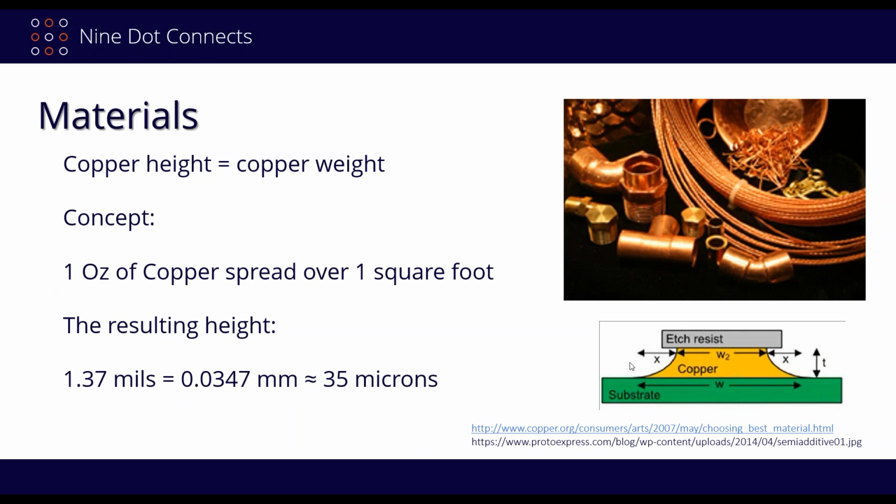What happens here is that, remember, you're working with copper sheets. You put an etch resist on top of it, and then you put this in a chemical bath, which in turn etches away anything that is not underneath the etch resist. And of course, that chemical does find its way underneath the etch resist as time goes on. So the thicker the copper is, the longer it's got to be in there, and the more interesting the shapes tend to be in terms of what you get as a result of a trace.